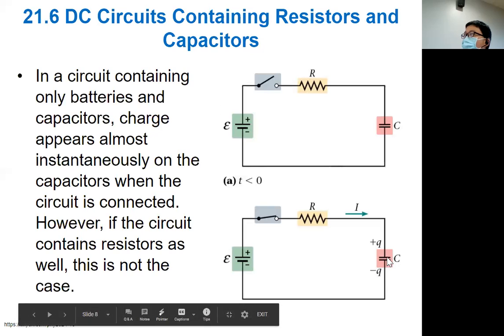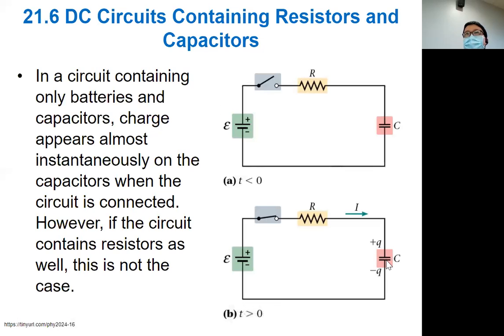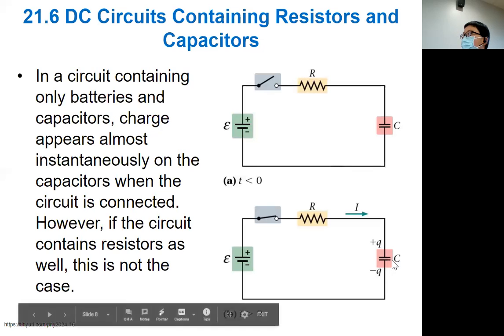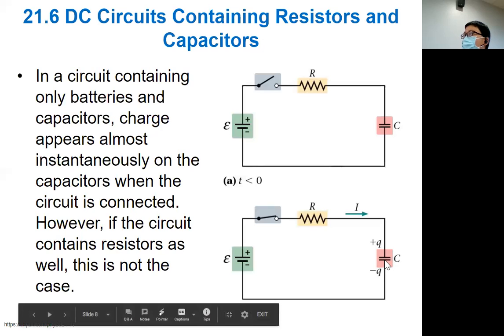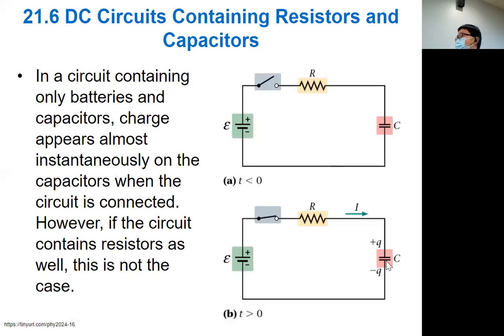For a capacitor, you have two conductive plates parallel to each other but not in contact, right? So this is an open circuit. It's not a closed circuit. So the current will not go through the capacitor unless you have a lot of voltage. If you reach the breakdown voltage of the insulation, then there will be current, but otherwise there will be no current. If not specified, we'll assume that you're not having current going through the capacitor.